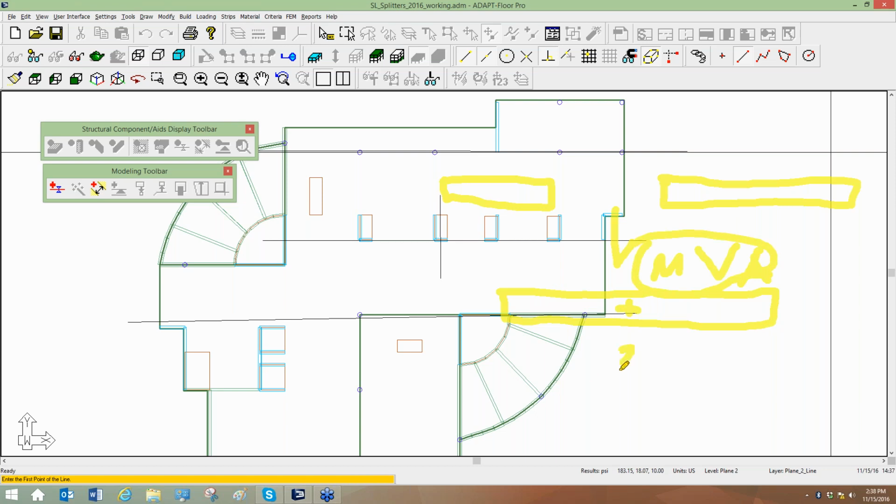So you need 2 square inches of steel for this design cut. But part of that steel has to be distributed to one side of the opening and the other side. And number one, most users don't get to that level of distribution. I just don't think people think about it, to be honest. And they don't go to that level of trying to dissect the results.